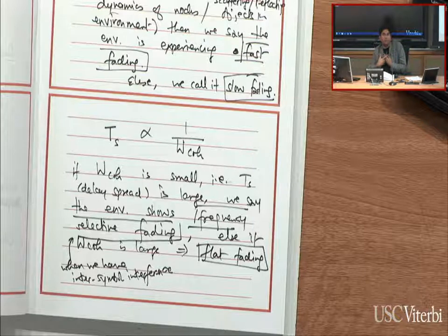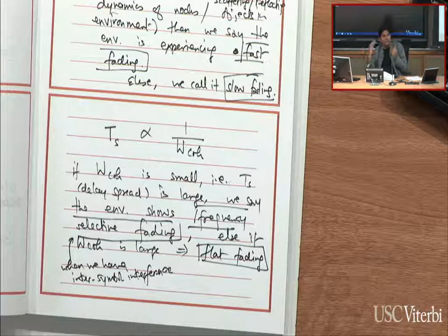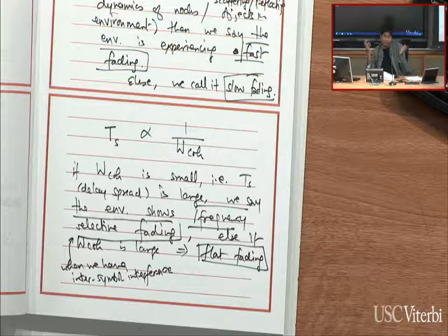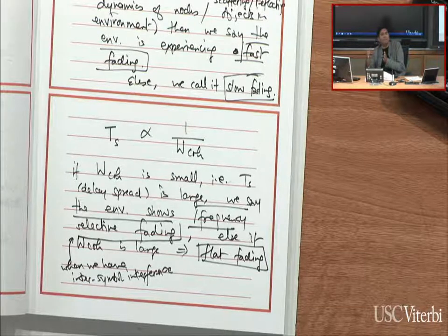In such environments where there are a lot of reflective surfaces, the multipath reflections show up many units of time later. Typically, these are in nanoseconds or hundreds of nanoseconds later than the original signal, or even sometimes on the order of a microsecond, and start smudging into the next symbol.